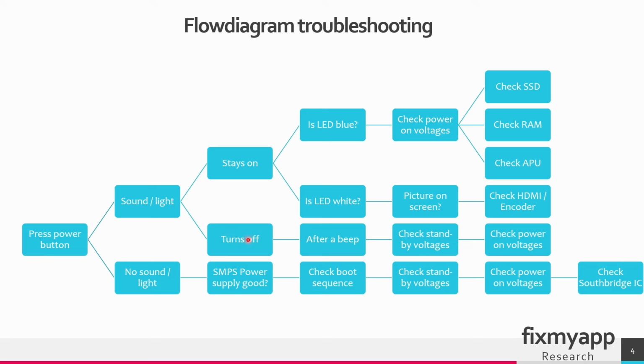When the console turns on and then off after a beep, then you have to check all the standby voltages and also all the power on voltages.